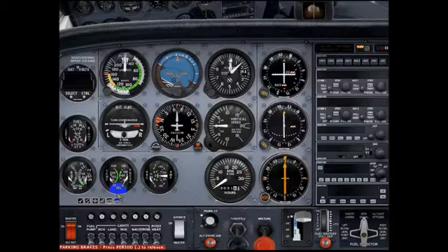Here, oil temperature. This is the oil temperature gauge. The green range is the temperatures that you want to be in. As far as temperature, on this side, you don't want to exceed 245 degrees, and then we have pressures. This is in PSI. We have a turn coordinator. We'll talk about that later. The attitude indicator is not running. It's not operating. Again, the aircraft is off.